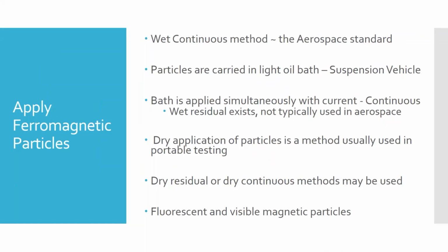And that whole process is pretty quick. So you press the button, you start putting liquid on the part, you draw the liquid away, and then you release the button. And it takes all of 1 to 2 seconds. You shouldn't be running the machine more than a couple seconds. Bigger parts may take a second or two longer, but you should never be running it for more than 1 to 2 seconds normally, maybe up to 3 or 4 seconds if you've got a really big part. We don't want to run that current longer than we have to. It magnetizes pretty quick.